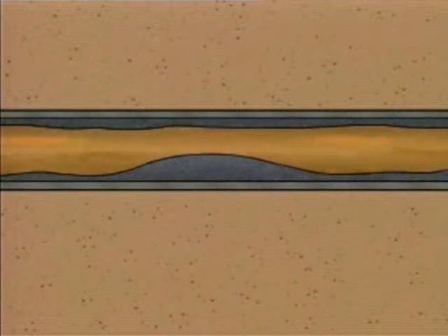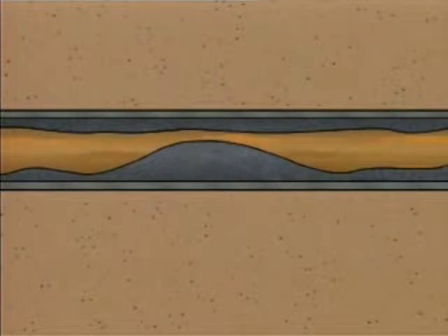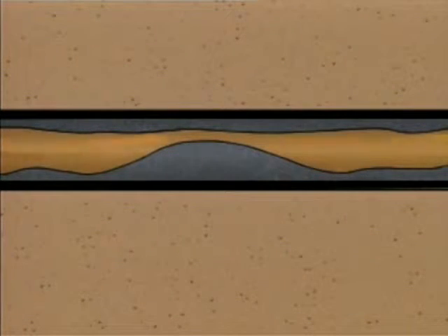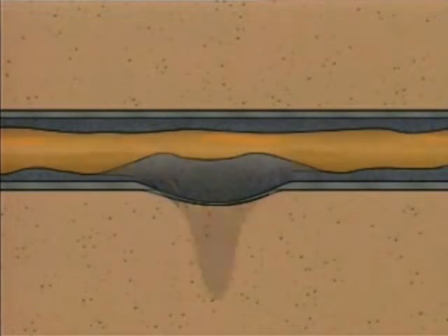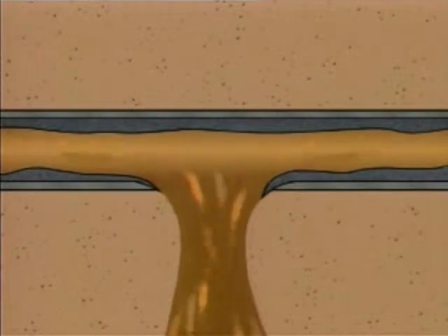Coking makes the inside diameter of a tube smaller, and it can restrict the flow of process fluid. It can also lead to heat transfer problems. Carbon deposits insulate tube walls, which reduces the amount of heat that is carried away from the tube by the process fluid. If this situation is not corrected, the tube could overheat, weaken, and eventually rupture.